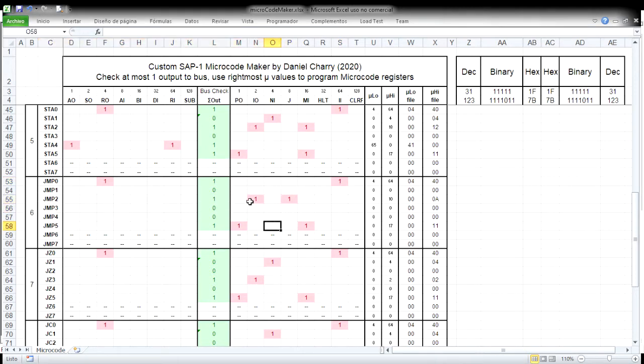We get what's on the instruction register, and we put it on the program counter. Because we are jumping anyway, there's no need to increase the program counter. There's no need to go to the next instruction. We just get what's in here on the instruction register and put it in the program counter, which is basically updating the program counter so that the next instruction is the jump.